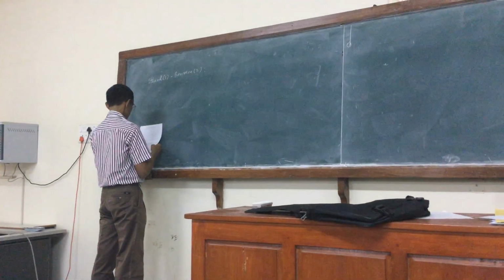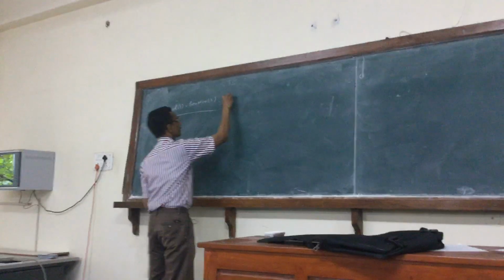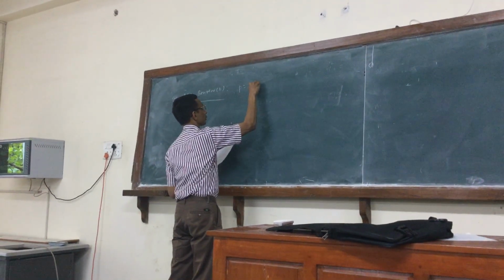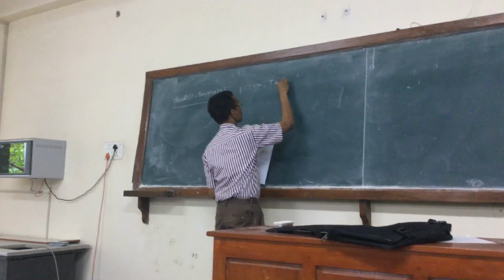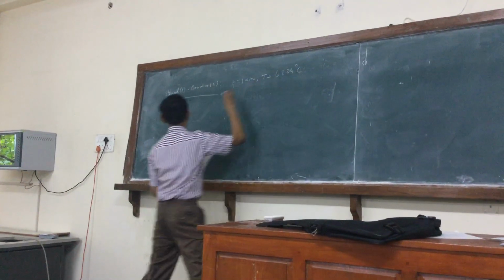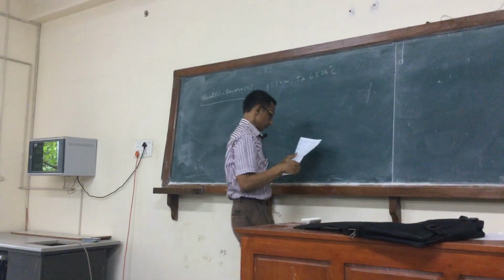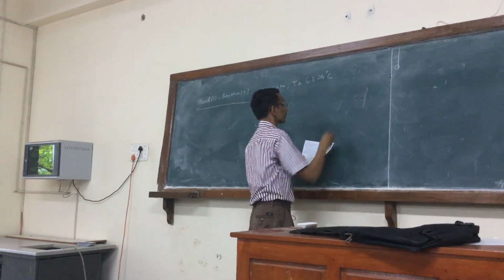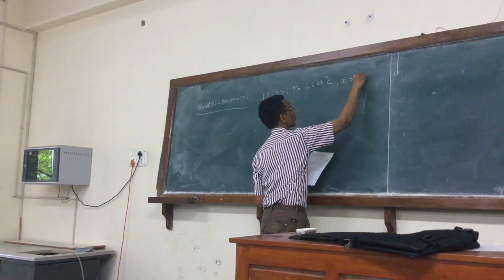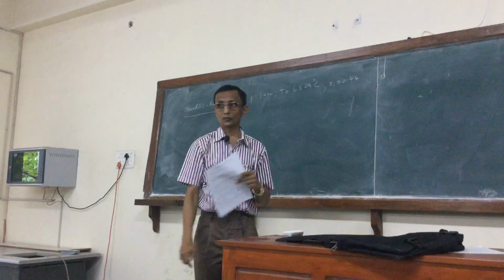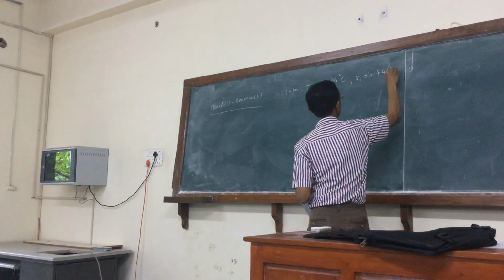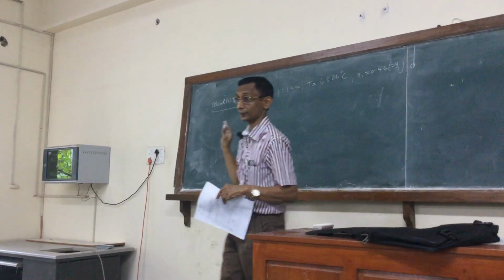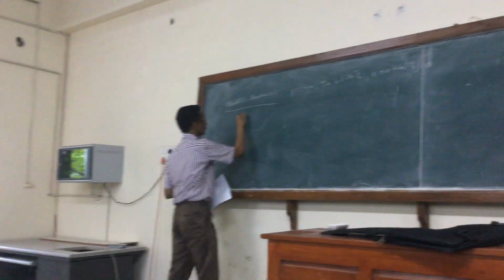So here we are given that this exhibits an azeotrope at P equal to 1 atmosphere, T equal to 68.24 degrees centigrade, and x1 is 0.44. So what is y1? Also 0.44. That's not given, but you should first know what an azeotrope is. Otherwise, you cannot even proceed one step.